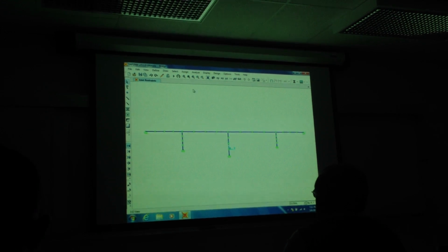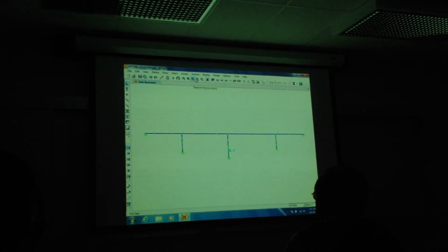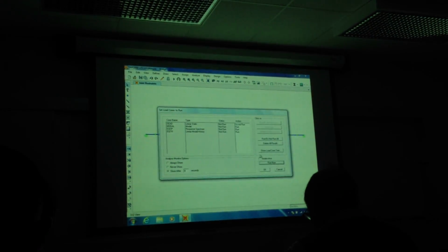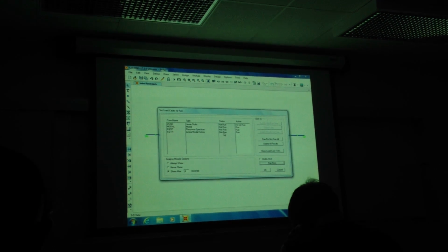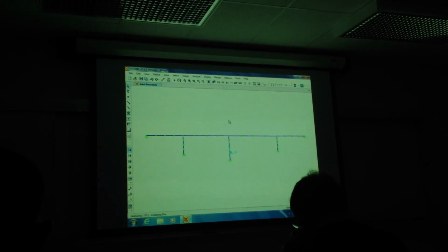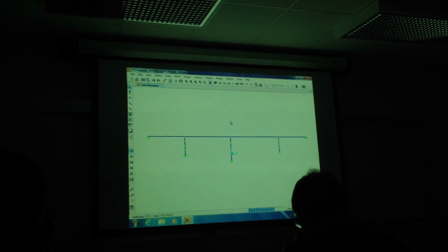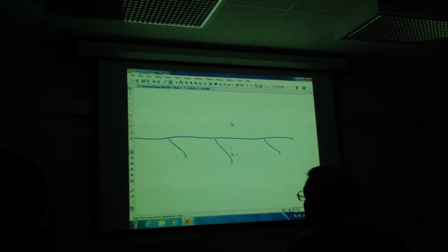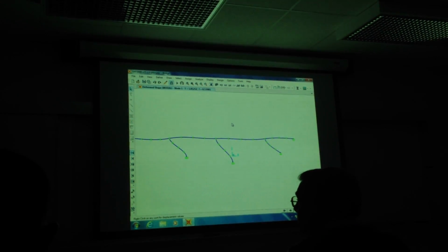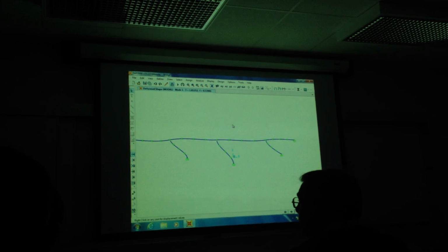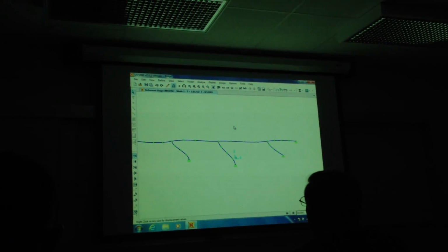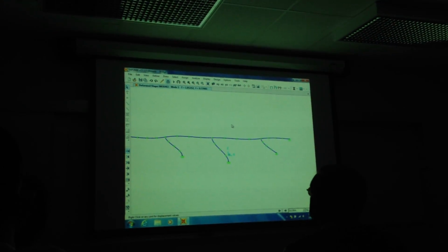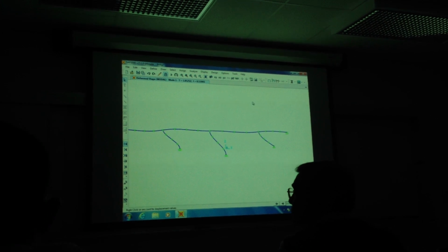So where were we last time? Running the linear elastic time history analysis, right? And how much displacement did we get at the top of the bridge? Maximum? 6 feet. No, I think from the earthquake it was about 0.4 feet, a little less than 6 inches, right? It was the ARS curve that we got, 0.6, which is about 7 inches. And that's because, let's see.